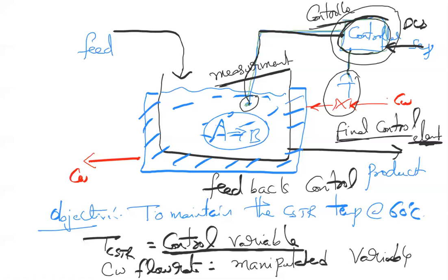So in the plant, let's say the plant sits one side, and the control room sits on the other side, at a different place. So there are a lot of cables coming from the plant to the DCS room, which bring the signals from the plant. Let's say what is the temperature of the reactor, what is the pressure of the reactor, what is the flow rate of the reactor. There will be so many signals coming in. Then the controllers will take the control action, and then send a signal back to the plant.